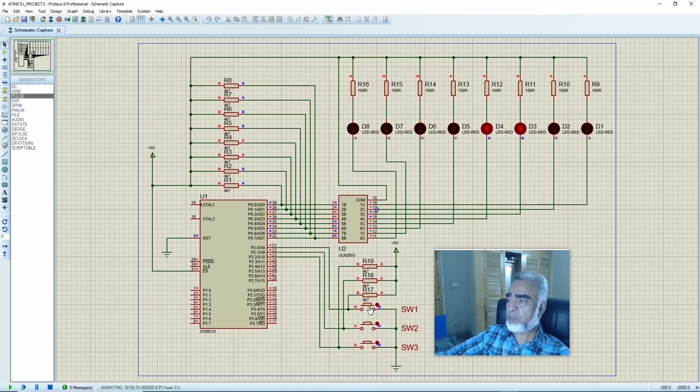And now if we press switch 2 once again, we can check the debouncing delay is less than the delay which we had in our previous program. So in this session we have learned how to write a reset routine for our counter program, and how to increase or decrease the debouncing delay for a switch.